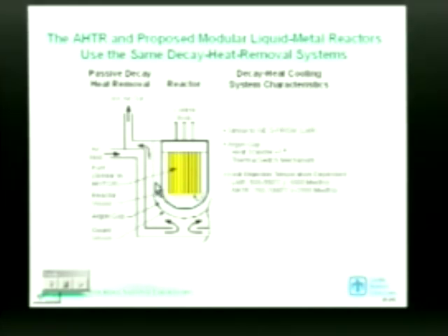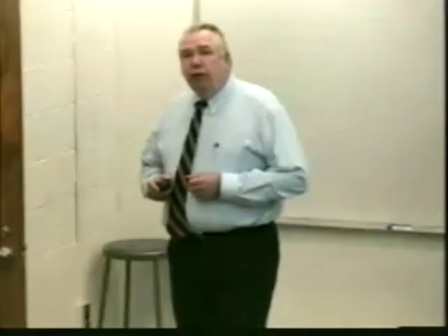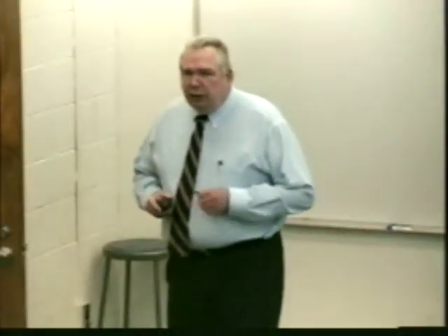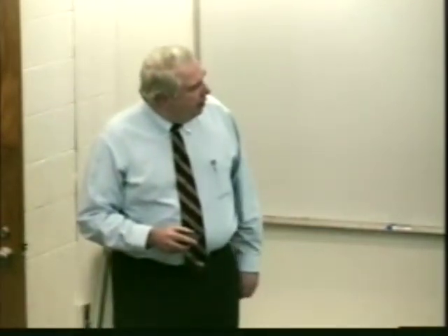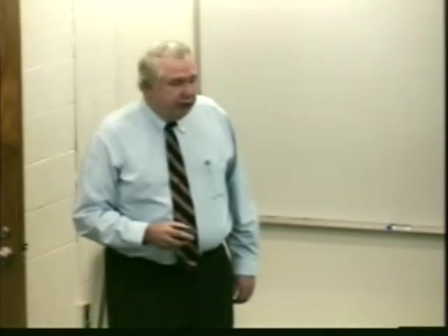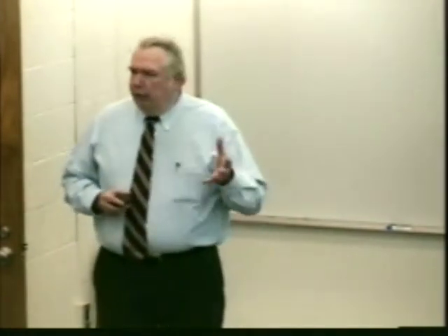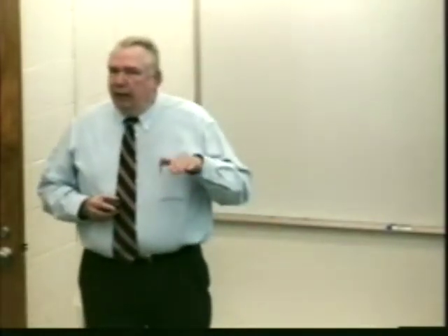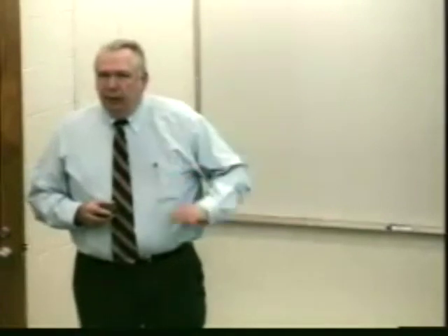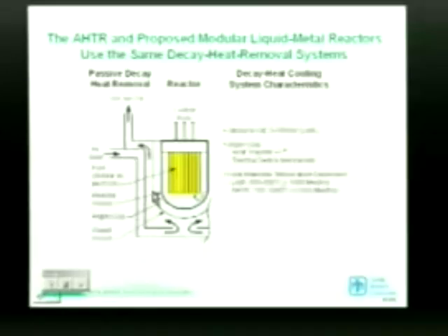Same philosophy. Now, what's important about heat transfer by radiation is that the amount of heat you transfer depends upon the temperature to the 4th power. So a very small increase in temperature results in a massive increase in the amount of heat that goes from the primary reactor vessel to the secondary reactor vessel. It's a solid state thermal switch mechanism. Low heat loss at one temperature, very high heat loss if the temperature goes up 50 degrees C. And of course, people have worked out the details of this for the PRISM reactor of General Electric.